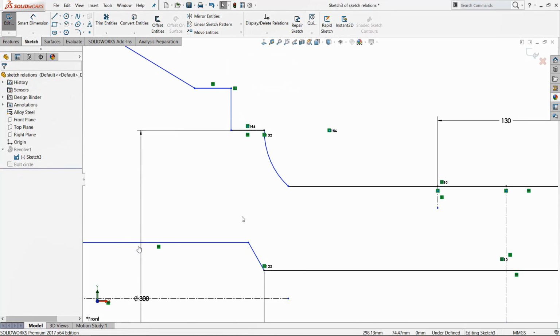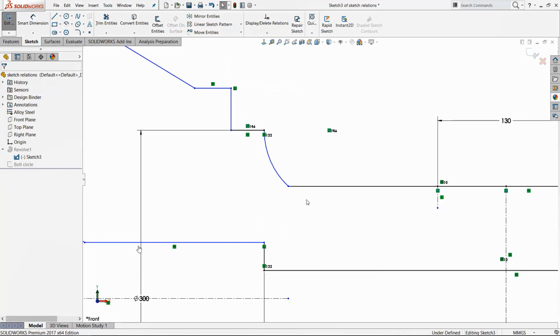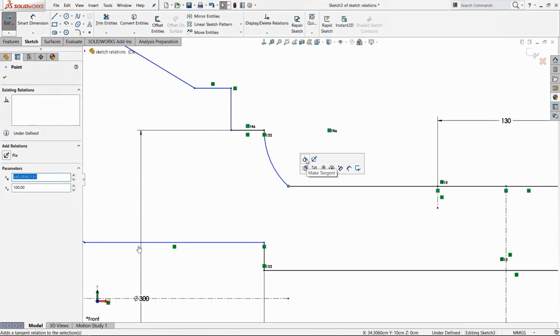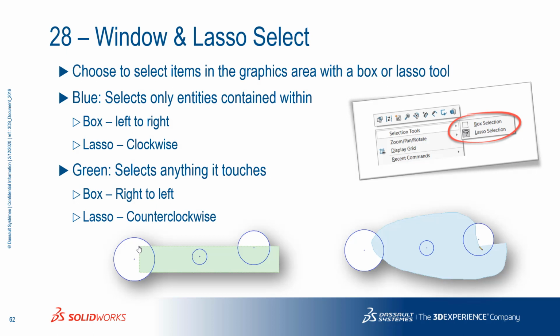Just click the shared vertex right there, and then the acceptable commands come up, and I can quickly add that. Here I'll add a tangent relationship. The key here is to just remember that that exists, because we get into our habits, right? And we've been working that way for years and years and years. I do that too. Just want to explain these things to you guys. It's going to save you a lot of time. Whenever I can remember it, I'm pretty proud of myself that I remembered that. I don't know if you guys have that feeling.